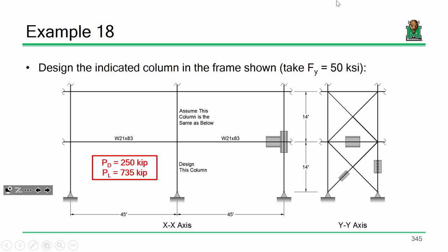On this story, the design's probably a little conservative because the taller you get, the forces on those columns tend to decrease a little bit. But from a constructability standpoint, it makes sense that this column and this column physically be the same piece. So you would erect, then erect another 2 stories, and that's how you build your frame. Does that make sense? Everybody okay with that? So that's not an uncommon assumption.